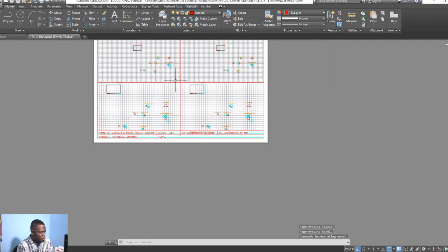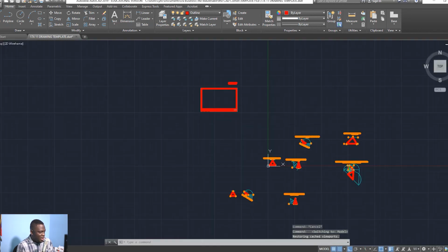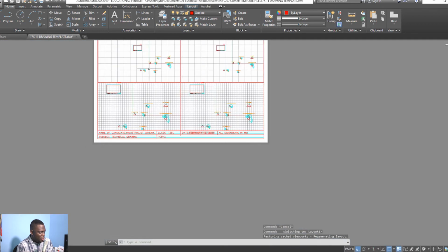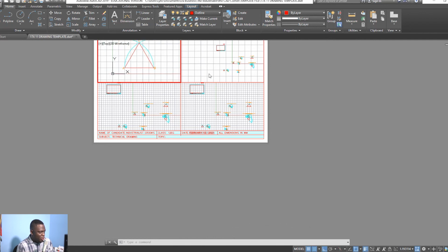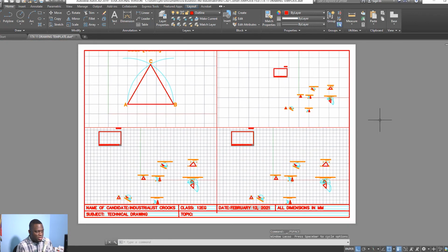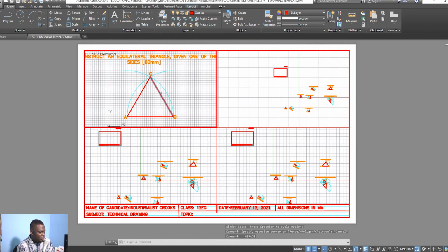And then you're going to notice something strange happens. All the drawings within your file that you have created appear. So all you have to do is double click in the viewport and scale them to fit inside the viewport window. You have to click outside the box here if you want to be outside the viewport and to move the paper around. If you try to just click and drag, you'll be moving the viewport. So to go back in there again, you double click, zoom in.